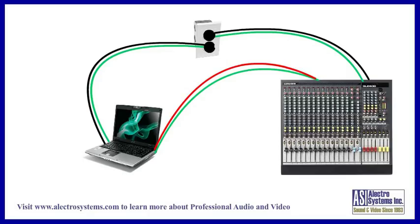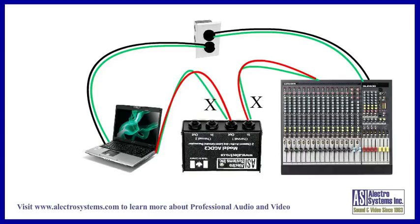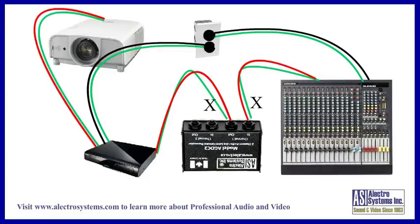In this example, unbalanced computer audio output is connected to the line inputs on the mixer. You are likely to experience a ground loop between the computer and the mixer, especially because the computer output is unbalanced. Adding the AGDC2 between the two will break the ground loop and at the same time fully electrically isolate the two units. The same is true for a DVD, mixer, projector combination.